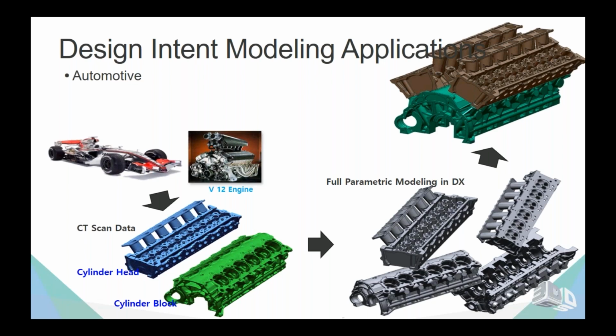So one of the competing points, or one of the major points of DesignX, is the ability that it has to not just extract modeling history and features from a scanned file, but also transition or send those files downstream into some other CAD systems, for example, SolidWorks, and rebuild those models there parametrically so that the end result is essentially a native SolidWorks part that looks like you had designed it from scratch.